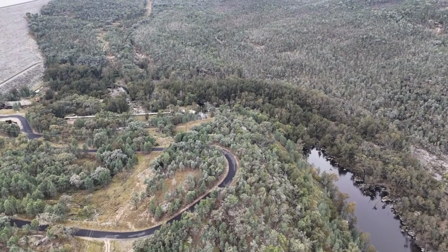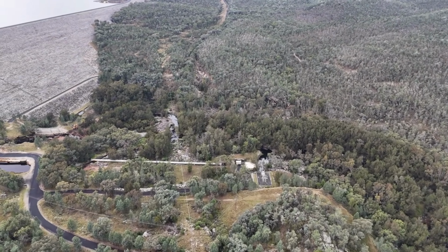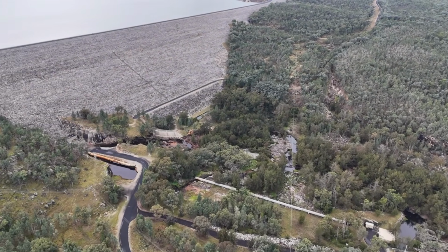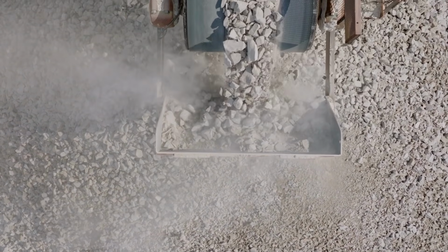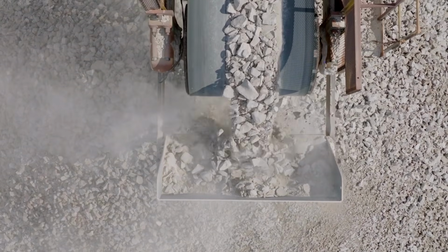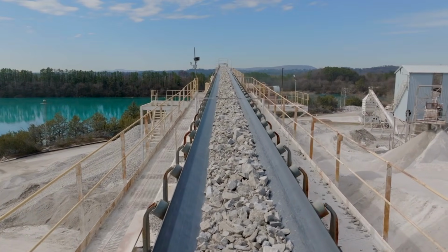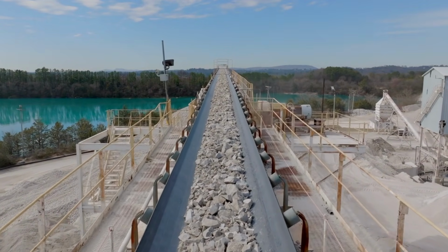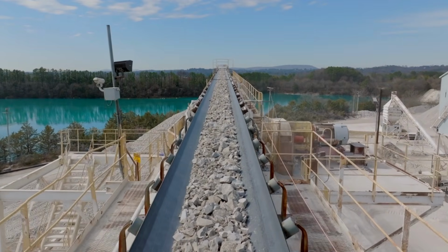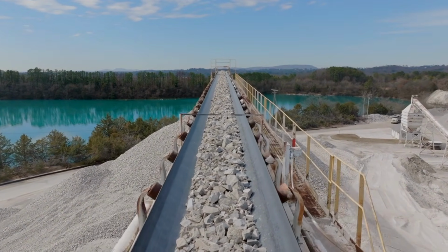But as the reservoir empties, the physics shift from a wave-dominated regime to a sediment-dominated one. The vanishing lake leaves behind decades of silt and mud. As the final stages of the break occur, this muck is pulled into the flow. This creates a hyper-concentrated flow that is much denser than water. Because the density is higher, the shear force, the product of mass and acceleration, increases.